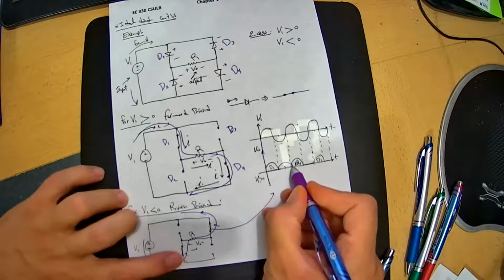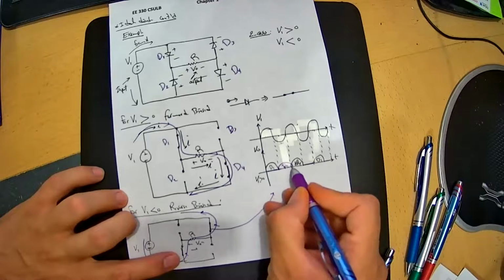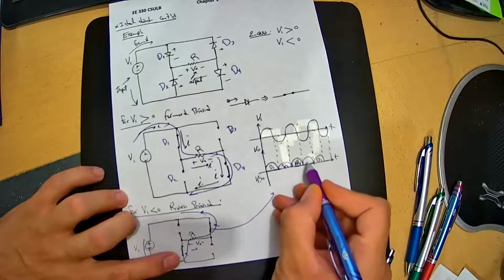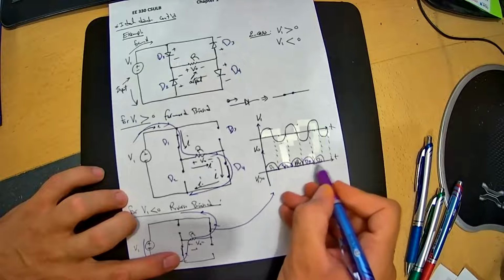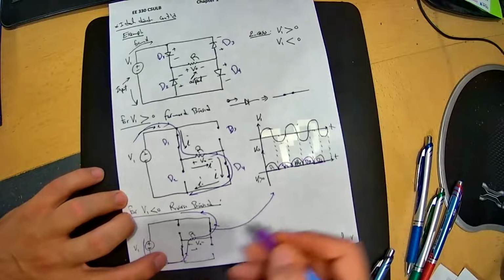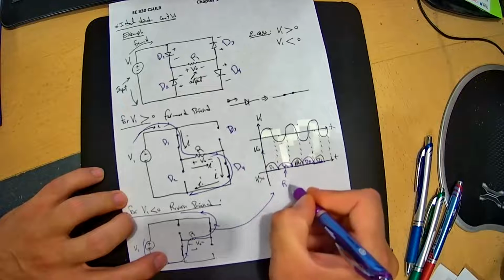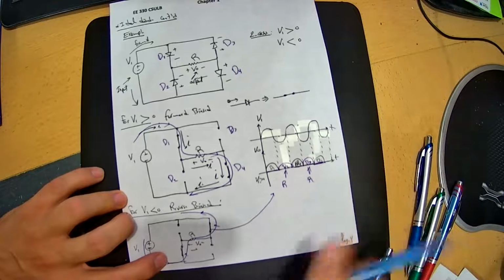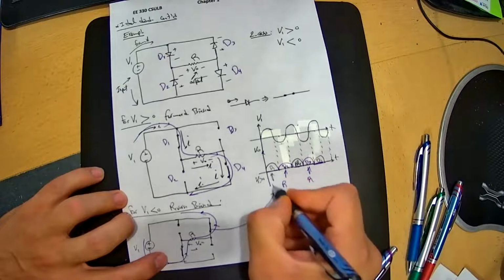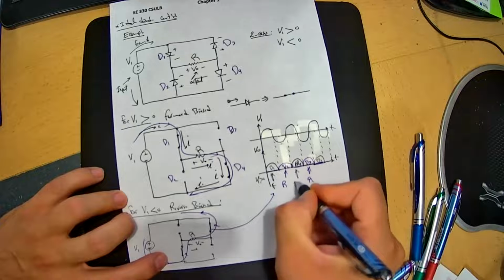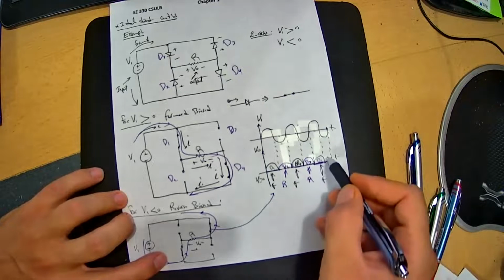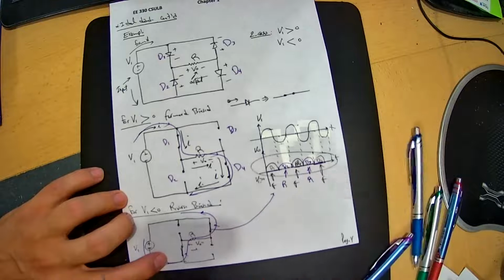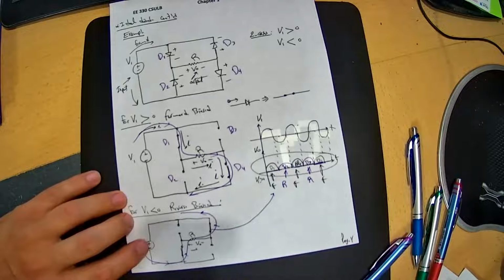This is D2. D4 will be off, and D3. And then D1 kicks on because it's going to be off on the reverse bias. So most likely this is reverse bias, forward, forward, forward. So my output signal will be clipped into a rectifier.